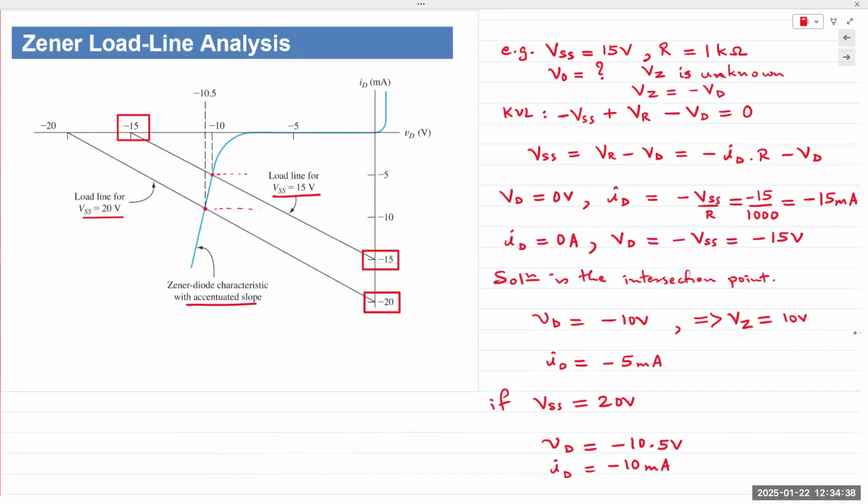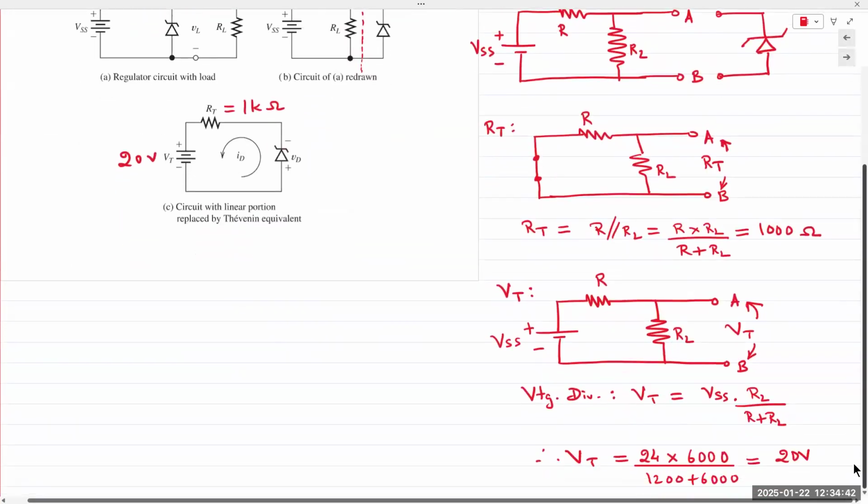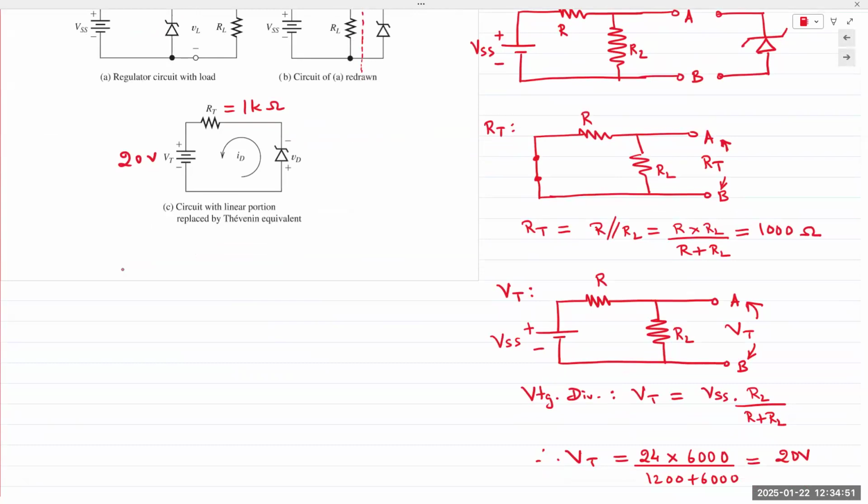All right. So where were we? Oh, so now we have a linear circuit, the same circuit that we analyzed on the previous page. Now we can apply KVL. If you apply KVL for load line analysis, we generate a load line for VT and RT.